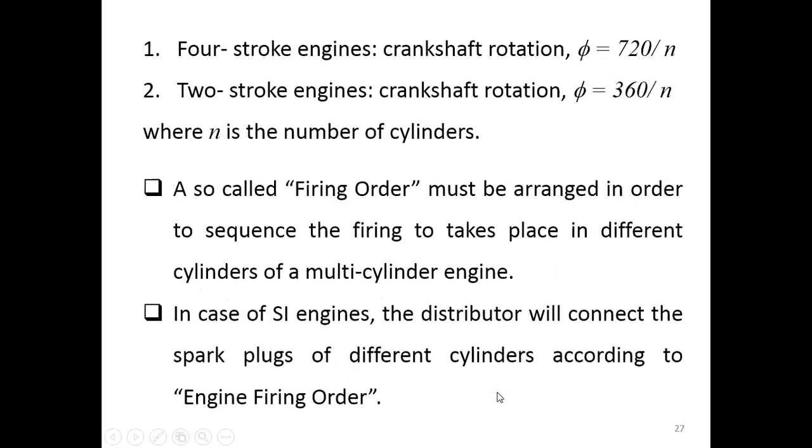For the 4-stroke engine, the crankshaft rotation will be 720 divided by the number of cylinders, because every 2 rounds of the crank, we need 1 explosion.